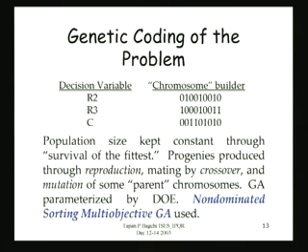And let me just show you how this was done. We used a technique that is available now to people who are working with multi-objective problems, and they are doing this using genetic algorithms. We are using GA now to create robust designs. And the technique is called non-dominated sorting multi-objective GA.